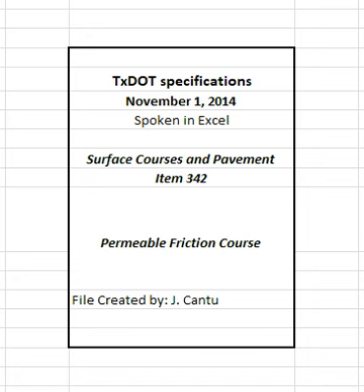Supply aggregates that meet the definitions in Tex 100E for crushed gravel or crushed stone. The engineer will designate the plant or the quarry as the sampling location. Provide samples from materials produced for the project. The engineer will establish the surface aggregate classification, SAC, and perform Los Angeles abrasion, magnesium sulfate soundness, and microdeval tests. Perform all other aggregate quality tests listed in Table 1. Document all test results on the mixture design report. The engineer may perform tests on independent or split samples to verify contractor test results.